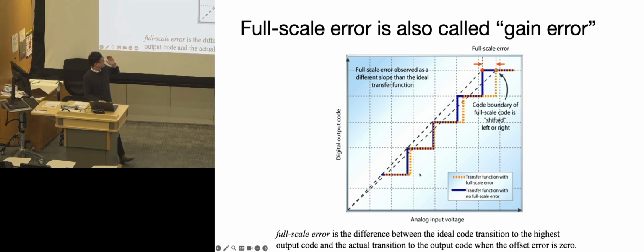So how do we calibrate this? This is also one of the easier errors to calibrate. Basically, we sample a bunch of known values and then look at the output DAC values. Then we use that to calculate a transfer function and calibrate the output, because in this case we are assuming them to be linear. So with a few known values, we are able to build a transfer function between them. Does anyone have any questions regarding the offset and the gain errors?